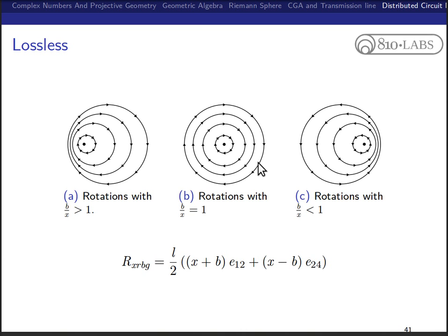Okay, but if we make something a little bit more susceptive, then we start to get a mismatched transmission line, and so we notice that the match point starts moving a little bit to the left here. And if we take this in the extreme, where basically there's no reactance, then you just get rotations in B, in susceptance, which is what we saw above, and this is a similar thing in the other direction, so more reactive.